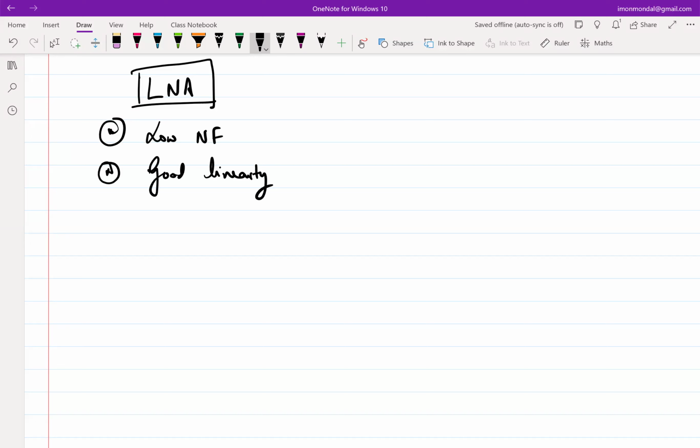It can get a lot of various amplitudes of input. Given that you have maybe a SAW filter upfront, still within the band you can get fairly high, different amplitudes of input, right? What else? Impedance matching, basically matching, right? So that is very specific to an LNA because it is seeing something which is coming from outside the chip, right? So without matching, you have a big problem. So matching.